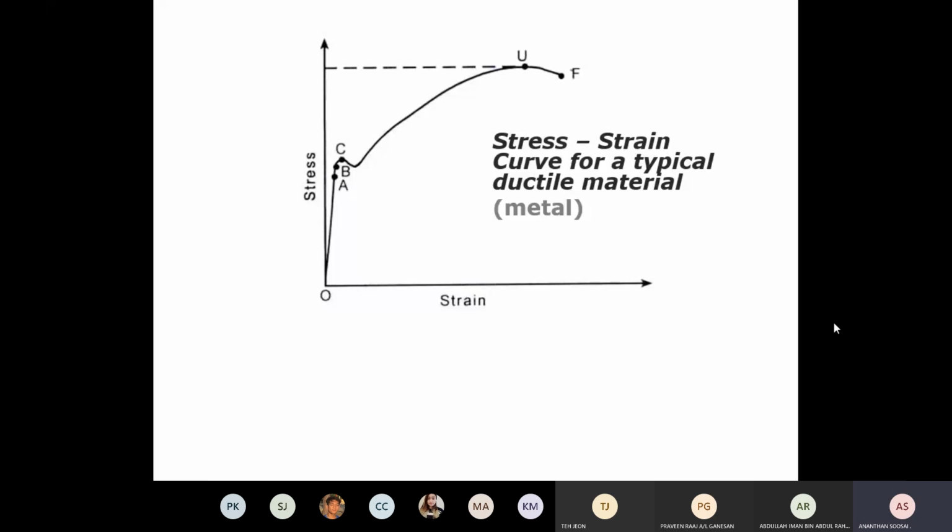Okay. Then series parallel discussion. We introduced new terms called stress, strain, Young modulus. Okay. What is stress? Force acting normally per unit area. Okay. Unit Pascal. What is strain? Is the ratio of extension to the original length. Unitless. Then what is Young modulus? Is the ratio of stress to strain. Okay. Unit Pascal. What does Young modulus measure? Stiffness of a material.